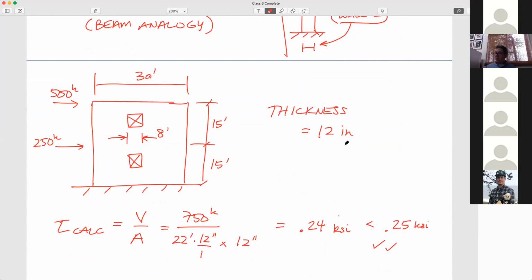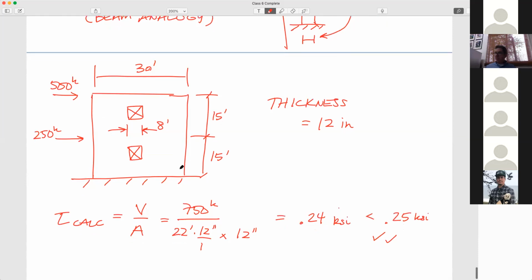And so here would be a 2-story shear wall structure. We've got some windows that are present. So this is 30 high and 30 long, so it's got good aspect ratio. And the openings are not huge, so we can think of it as if it's one shear wall.